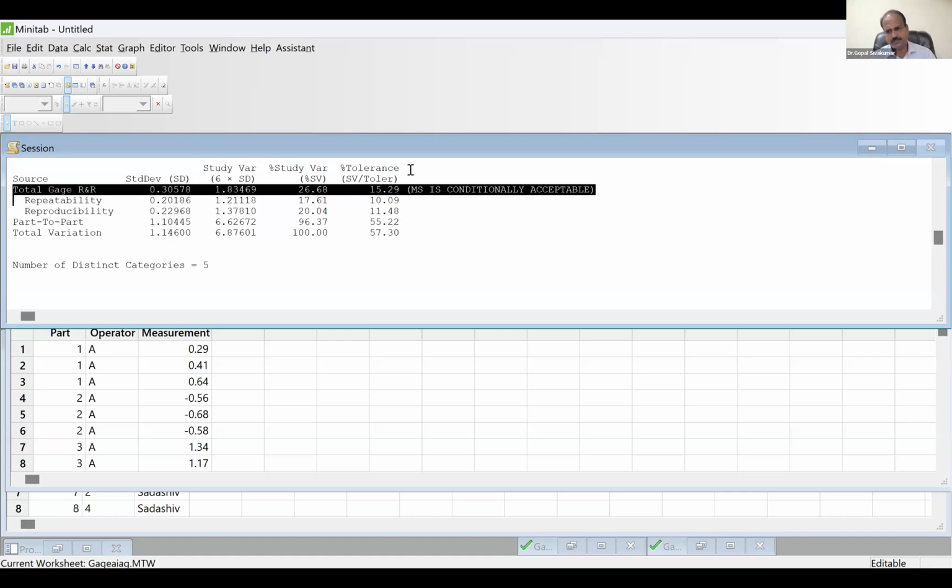Do you understand? If control limits are closer to the spec, then it is better to avoid using the same measurement system. We have to go for a better measurement system because the uncertainty created by the measurement error can lead to wrong decisions. A good product might get rejected or a bad product might get accepted. All these possibilities are higher.